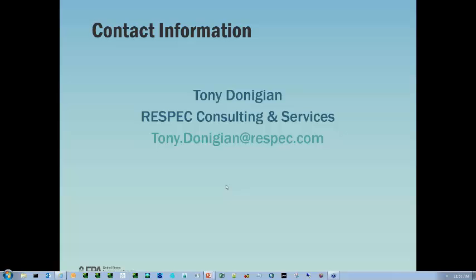The next question asks if there are any guidelines or recommendations for choosing when to turn on the nitrate or phosphorus modules as opposed to PQUAL. In any first application, it's probably best to use PQUAL, the simplified approach, unless your watershed is dominated by agriculture and you have enough information in terms of fertilizer application rates and crop yields and things like that that all go into doing a nutrient balance on the agricultural areas. Even if you're going to go that route, ultimately it might be worth doing a first approximation using the PQUAL routines, just to get a sense of what range of loadings might be appropriate for what you're seeing in your in-stream concentrations.